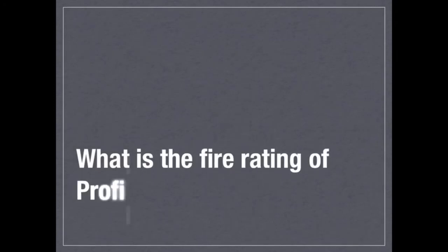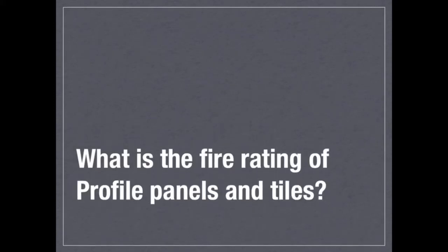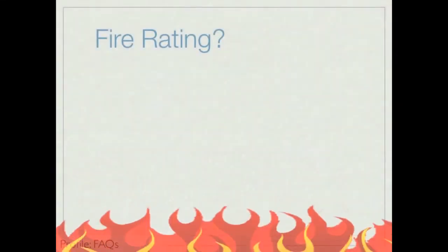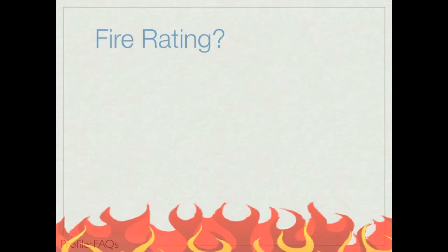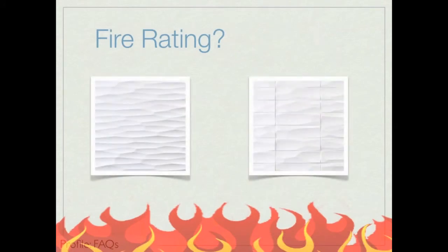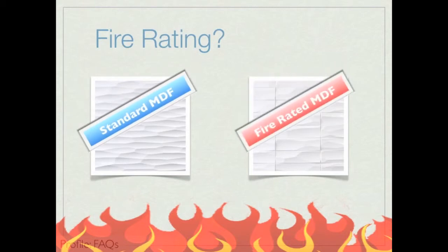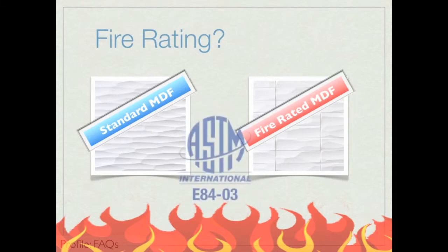What is the fire rating of profile panels and tiles? Well, when it comes to fire rating, there are two specifications that are available: standard and fire rated. Both of these types have been tested for flammability and smoke with the ASTM E84 standard, and the results were favorable.